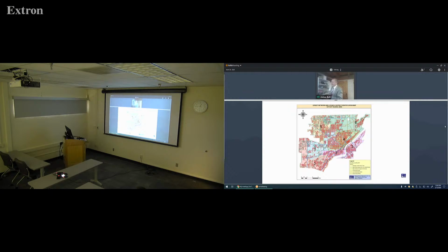Therefore, the pavement management system, one of the decision-making processes, also helps show how the pavements are performing within each district. Therefore, we can tag the data and analyze the performance of the arterial, collector, and residential network within each district also, and see how one district compares with the other district.